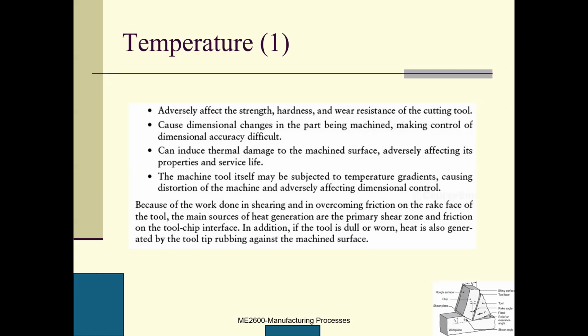The third one can induce thermal damage to the machined surface, adversely affecting its properties and service life. Thermal damage: if the workpiece in the neighborhood of this cutting area absorbs a lot of heat, what will happen? It expands substantially.